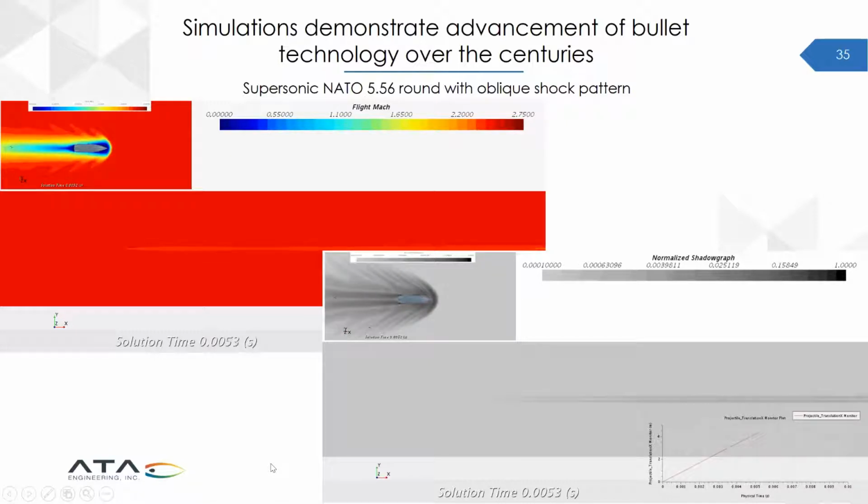But for all of these simulations, basically for all three of these bullets, you run the script, you bring in the new geometry, update all of your settings, and then execute your operations to rebuild your mesh with the new geometry, and then run, and you can spit out all of these same post-processing views with each individual bullet.